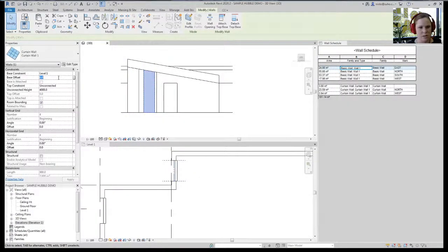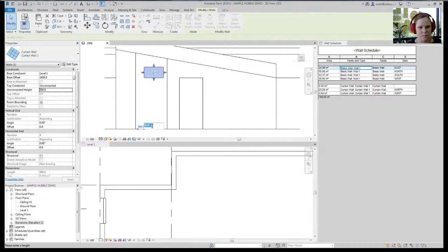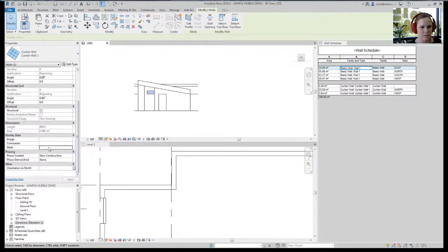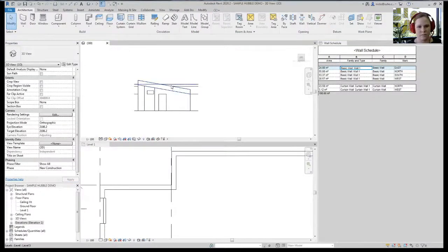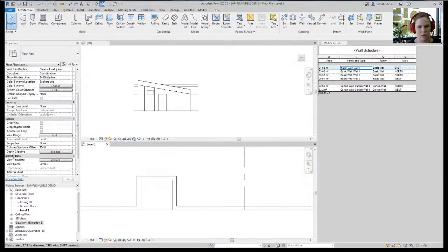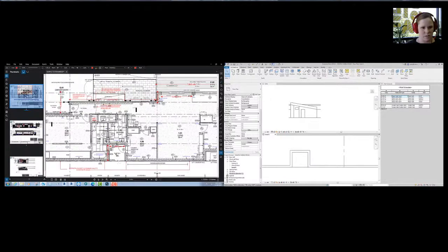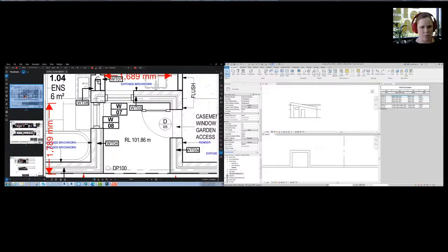Okay, and we're going to change these dimensions as well. Good. So you'll be fairly exact on this. Orientation is west. Great. Now I've got a little courtyard. So we need those measurements as well. I'm just going to estimate, because I don't have the section handy, that they're at the same height for the bed, for the bathrooms, because we have a bench there and they're just above bench height. And the other one I know is a door to go into the bedroom.